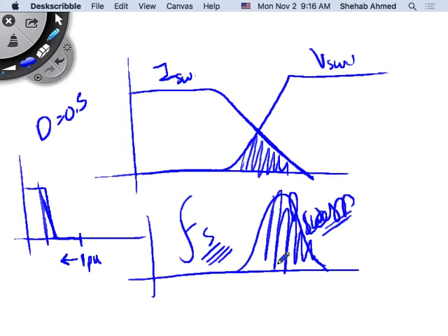The most efficient package possible will be something with a large inductor, a large capacitor, and a very low switching frequency, because then you don't have switching losses playing a role, and you don't have large inductor resistances and capacitor ESR. So you end up with something this big. But now you want something this small, doing the same function, converting 10 volts to 5 volts. How do you do that? It's an optimization process.